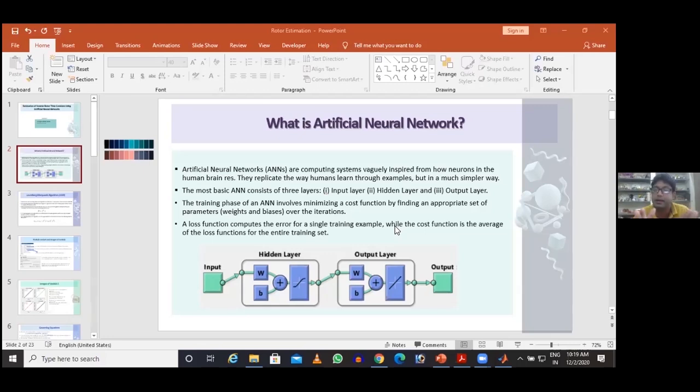Immediately the paper will tear out and the entire pulp will go waste. So in such a case, the dynamic response of the prime mover should be very, very accurate. There should not be any undershoot, there should not be any overshoot. It is a nearly perfectly sharp increase. The rate at which I change the excitation, the output response of the machine will nearly follow the same path. That means the dynamic response of the system is very good.